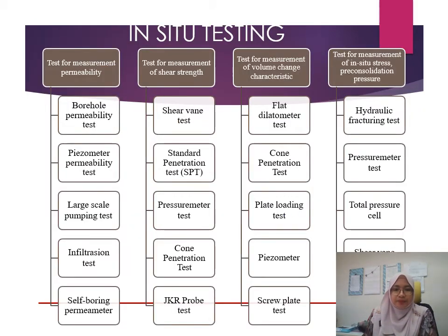Okay, so this is the list of in situ testing or field testing that you can perform on site to determine all of the parameters or soil properties. We have tests for permeability, tests for shear strength, tests for measurement of volume changes, and also tests for in situ stress and pre-consolidation pressure.